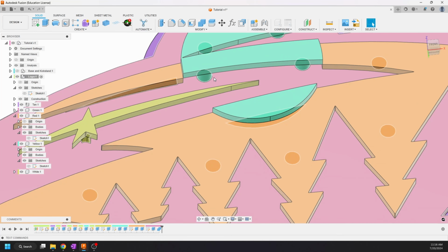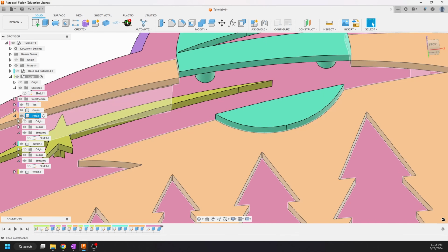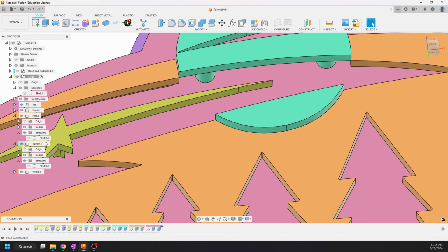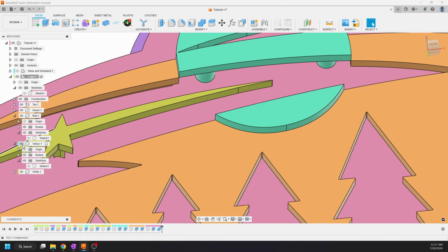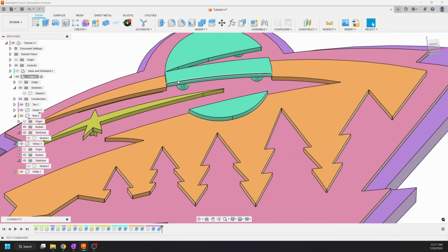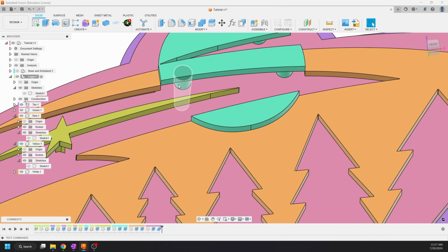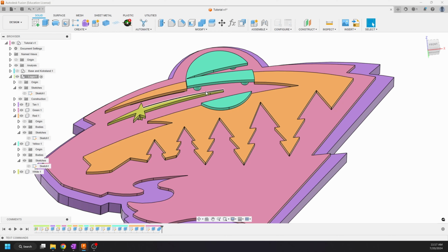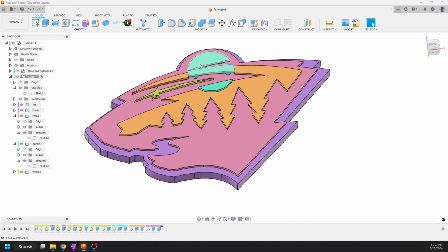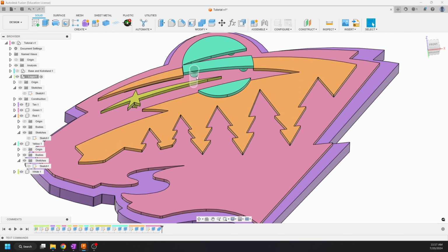Now you can see that you have that dark line there. If we turn off yellow, you can see that we've made the cuts. Again, for 3D printing, that is an exact size cut for this exact size pen. So we will be adding some tolerances, but that's much easier than you may anticipate because we add all of the offset tolerances onto the pens themselves.